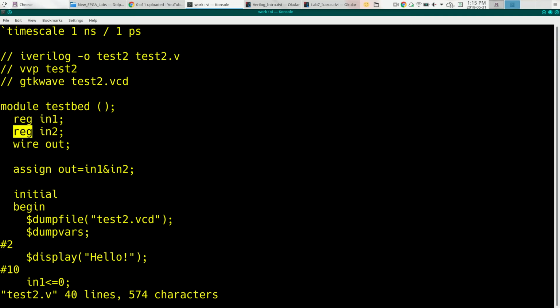So we need to move towards what we call a test bench or a test bed. And a test bench is a way to take a module we've developed and say what we want to do with the inputs, what we want to do with the outputs. It's basically hooking up switches and LEDs, but the software version of these.